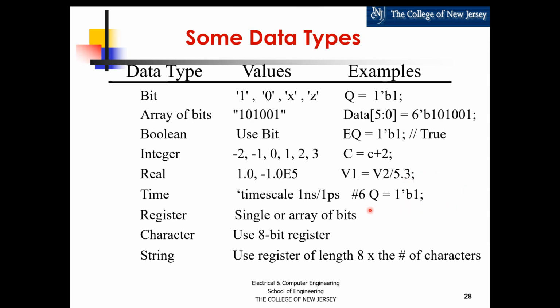So in your test bench, you're always going to have this directive as the first line. Backtick timescale 1 nanosecond, in this case, I mean, it can be different units, slash, in this case, 1 picosecond. The first number is that you are declaring the unit of time that you're going to be using in your design.